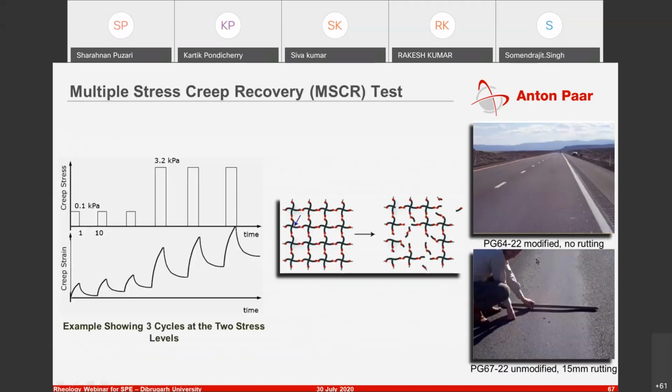And then the important point here is that those things are for actual asphalt original binders, or even the aged binders, but it doesn't matter. I don't say they're one and the same, but they haven't been modified per se with any polymer addition. So what happens is that nowadays polymer is being added, and those kinds of tests are not going to give you much information about the effect of polymers on either the fatigue behavior or the rutting behavior.